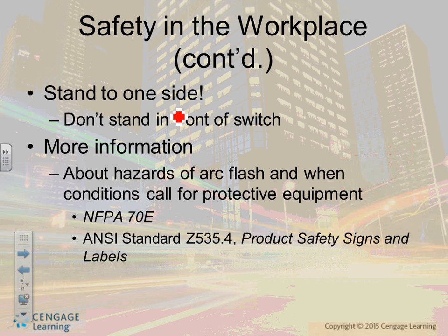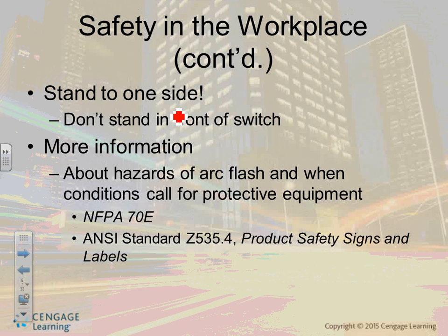A couple of hints. You guys are not electricians, but again, you will be with electricians in the field. They always tell you guys don't stand right in front of the switchgear. Anybody know why? You have a panel, they call it a box, right? What happens if you have an explosion in the box? When you have an explosion in the boxed area, it will go to the easiest side. The easiest side is where the panel is open, right?